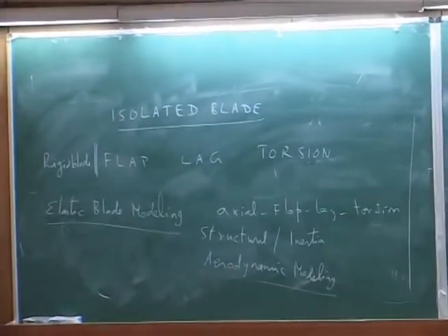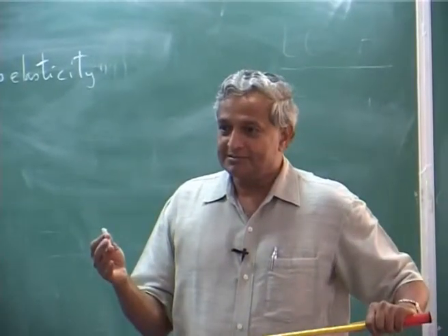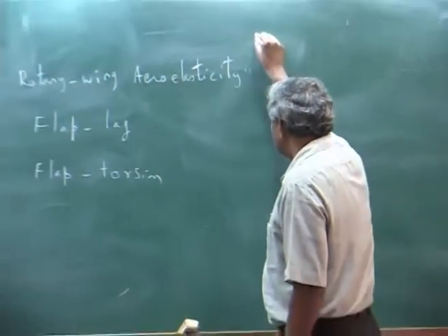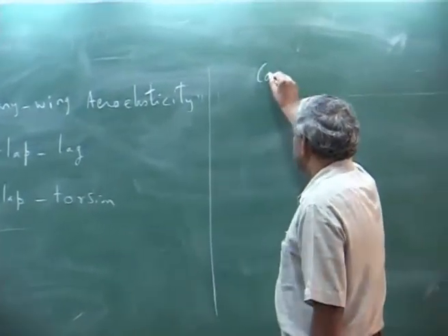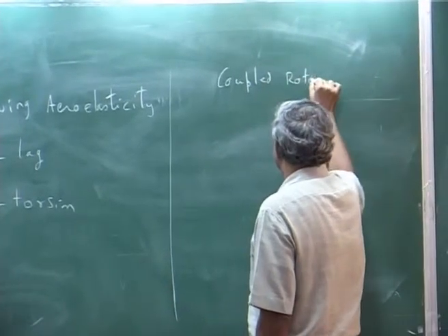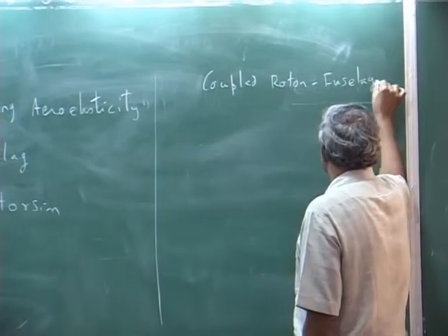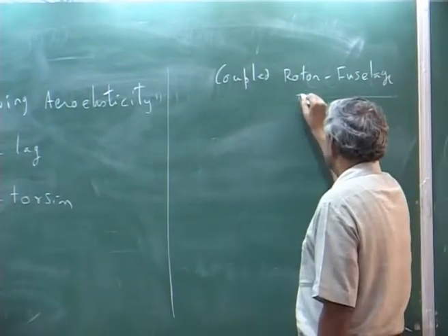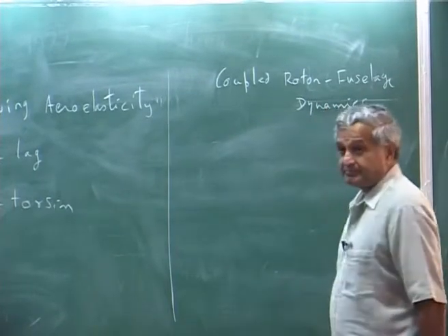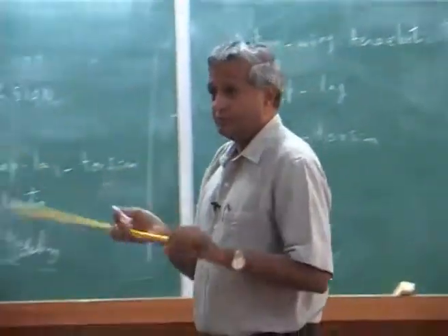You are only solving the blade problem. But in a helicopter, it is a rotor. That means I have to go for coupled rotor-fuselage dynamics. Okay. That means the fuselage is shaking, the blade is moving.